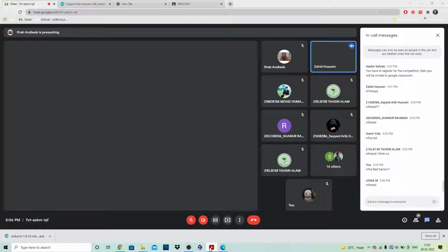So what happens is, if this infrared sensor detects something, then as soon as the wave comes back, it will turn this pin on, it will make the pin high. So that is why we are using this if statement. If it's telling high, we will print it. If it's low, we can print "path is clear". So we are storing it in a variable called has obstacle, and then we are checking if that has obstacle variable is high or if it's low.